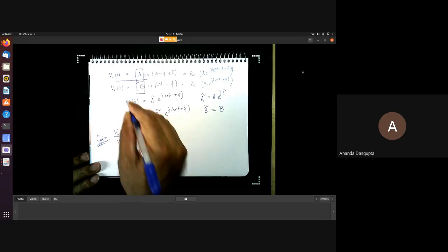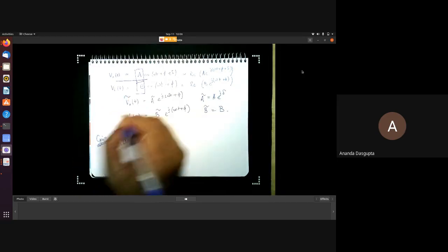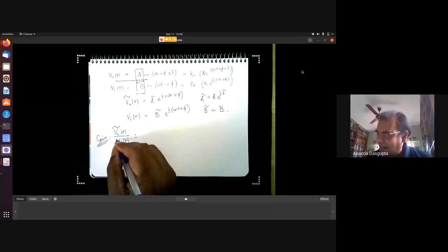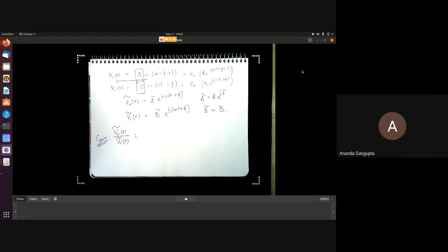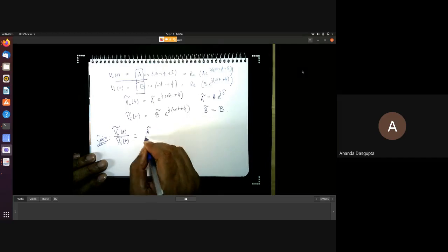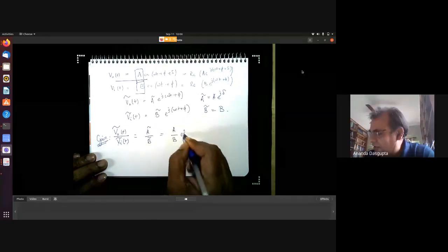So if I just divided these two, the complex voltages, which I'm not, okay, since we are on the same page, at least we should write the complex voltages with tildes, just to remind ourselves for the time being that they are complex. Later on, we just keep on using complex voltages all the time, so we don't even make the distinction. So we should write Vo tilde by Vi tilde. That of course is A tilde by B tilde, and that is A by B times e to the j delta, right?